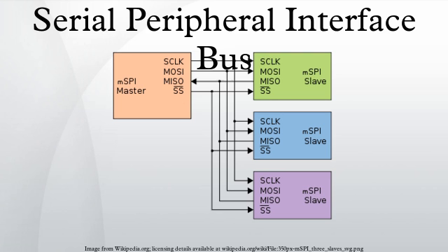Out-of-band chip select signals are required on shared buses, no hardware flow control by the slave, no hardware slave acknowledgement, supports only one master device, no error checking protocol is defined, without a formal standard, validating conformance is not possible, only handles short distances compared to RS-232, RS-485, or CAN bus, many existing variations, making it difficult to find development tools like host adapters that support those variations.